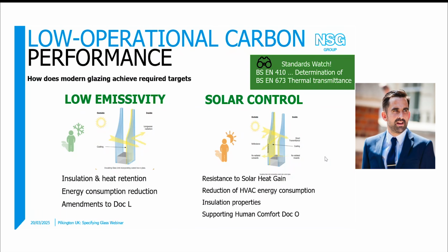Solar control glass coatings, they'll insulate just as well or better than low E coatings. And in addition, they will control the amount of heat buildup through the solar heat gain. This is obviously particularly important in projects where you have a large expanse of glass, where there's a reliance on HVAC air conditioning, and that's looking to be reduced, where human comfort is a factor.